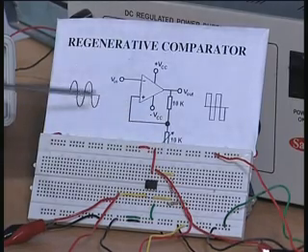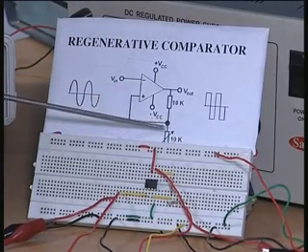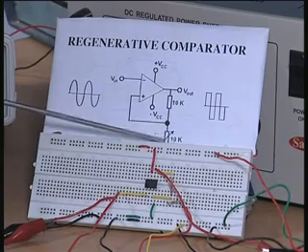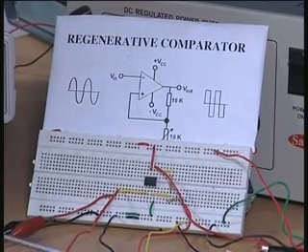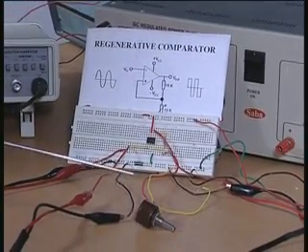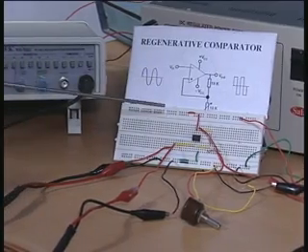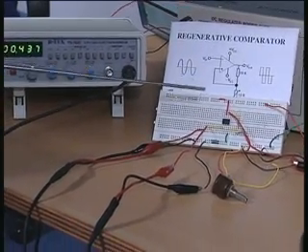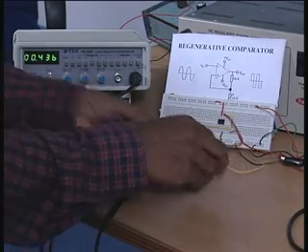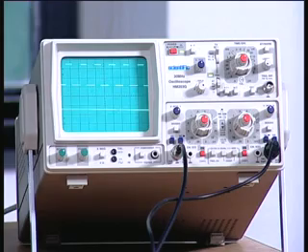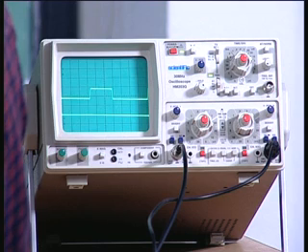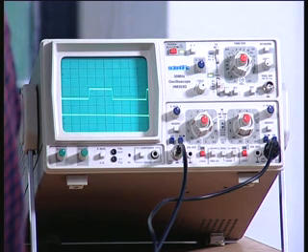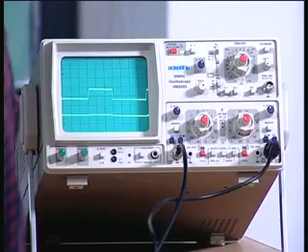For demonstrating to you that the V reference depends on the potential divider, in this place I have connected a 10K potentiometer. Therefore, now I am going to vary this potentiometer, and when I vary it I want you to observe the output of the oscilloscope to see what happens. So, now please observe the oscilloscope. Now I am going to vary this, see what happens. You can see the width is changing corresponding to these variations. When I vary this nearly by half scale it is changing.